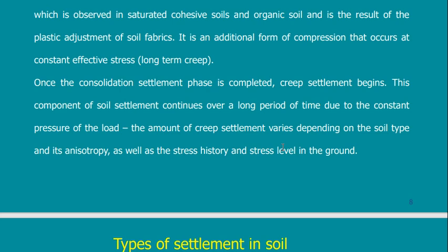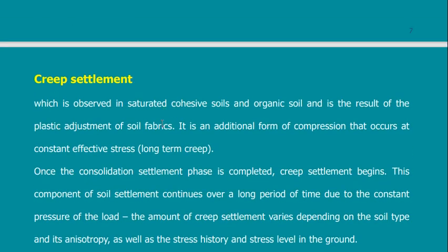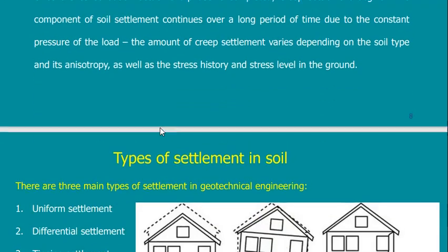So it depends on many factors, but in most cases the amount of creep is small compared to the immediate settlement or compared to the consolidation settlement. So it depends on the accuracy of your solution of any problem. Do you want to consider the creep settlement or not?